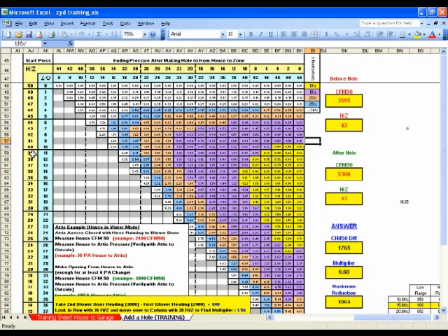One way of doing it, we could temporarily seal off some of the roof vents. In this example, the amount of roof vents is equivalent to about 6 roof vents. If we sealed off 2 of them, then that would move our number down farther along here, and then when we added the hole, it would have a bigger effect because now that attic is tighter, and that would move us over into this gold zone. So there are a few tricks that you can do to get your pressure number measurements to become more accurate. If you need finer definition on how much leakage there is, there is a way to do that.